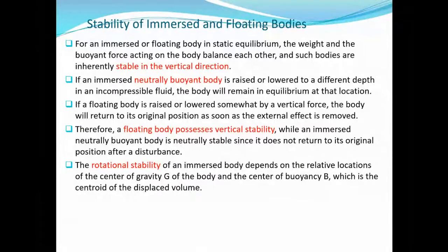Now, let's apply this to the stability of immersed and floating bodies. The same concept of stable, neutral, and unstable equilibrium. For an immersed or floating body in static equilibrium, the weight and the buoyant force acting on the body balance each other, and such bodies are inherently stable in the vertical direction.